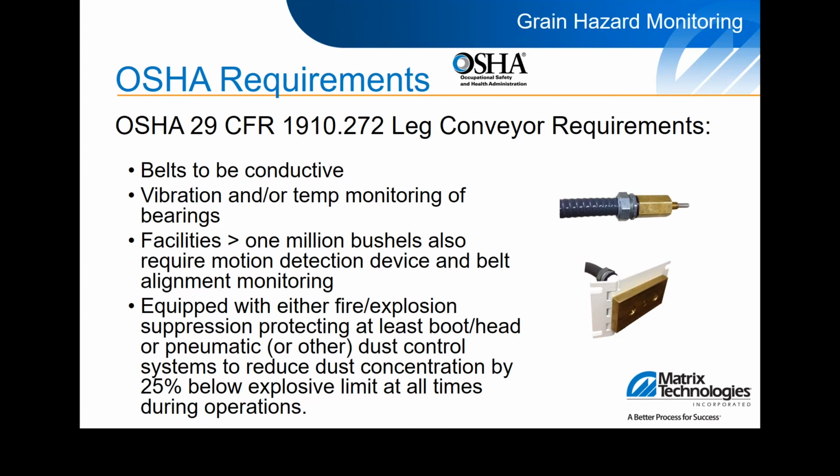At a minimum, best practice on conveyors is to monitor bearing temperatures at the tail and heads of the legs. This is done by installing bearing temperature sensors on both sides of the conveyor. If knee pulleys or take-up pulleys are used, typically these are also monitored as they provide a separate potential heat source for issues to reside. A network of devices is typically installed to monitor these sensors, and it can be provided from manufacturers such as CMC, 4B, Electro Sensors, and many others.